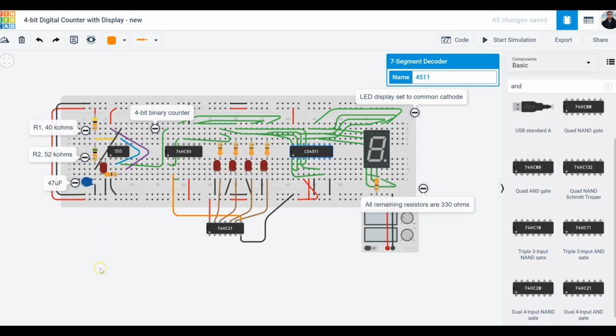How do you set a delay? In this project, using the 555 timer in this configuration, these are not just random values for the resistors. There is a math behind it. How do we choose the values of these resistors and capacitors such that this configuration generates a trigger moment, or a delay, every 1 second? Every 1 second the output of the 555 timer goes high and then goes off. Every 1 second it generates a pulse.